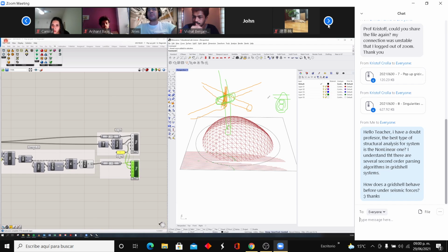If you have the knots that they're making here, they basically tighten themselves up. So what they do is they have this technique where you put your wire around it, and then you start to wind it. And as you're winding it by hand, the knot tightens itself up. And at the very end, you take the end parts of your rope or of your wire, you put it underneath and you slide it underneath the bamboo and the wires again to tighten it up even more. It's like a Boy Scout knot that you would use if you would make your tents or whatever. So it's quite a standard knot that tightens itself up a little bit. If bamboo shrinks because of humidity dissipation, then you might need to go around and retighten a few of those knots.